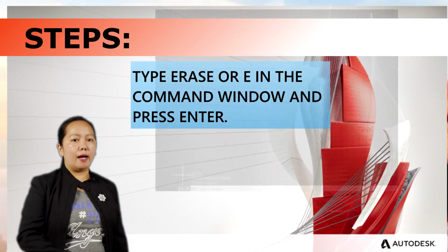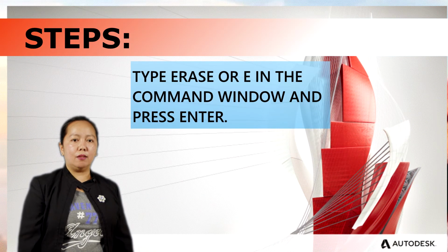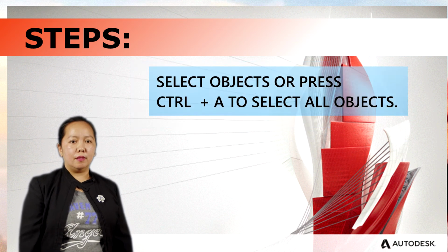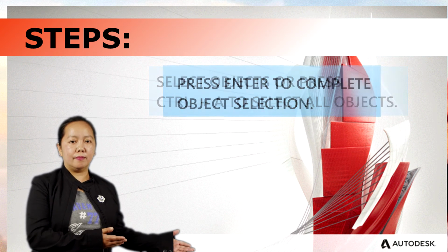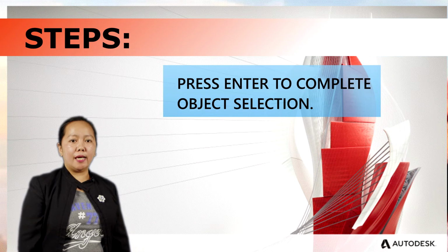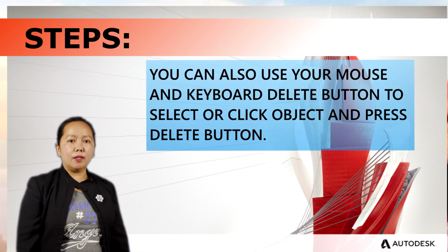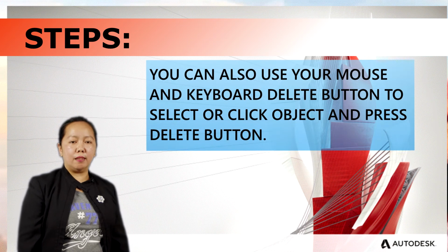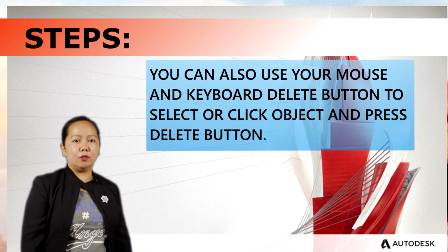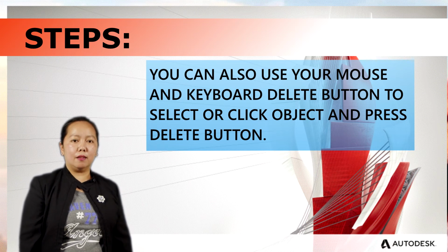Steps. Type erase or E in the command window and press enter. Select objects or press Ctrl A to select all objects. Press enter to complete the object selection. You can also use your mouse and keyboard delete button to select or click object and press delete button.